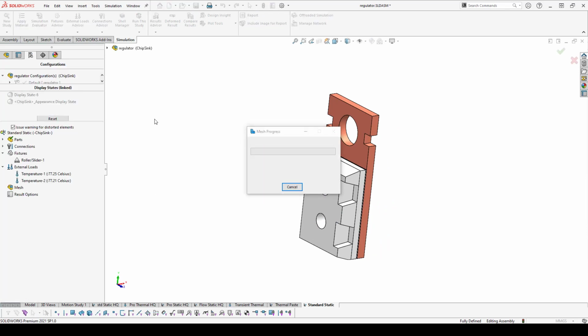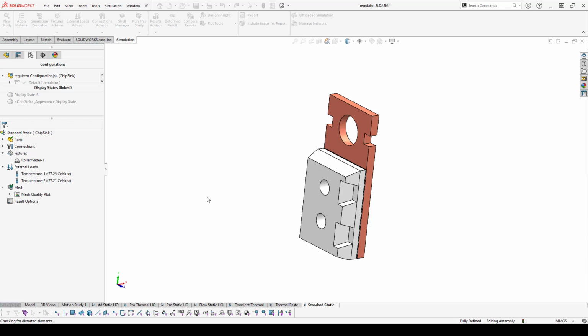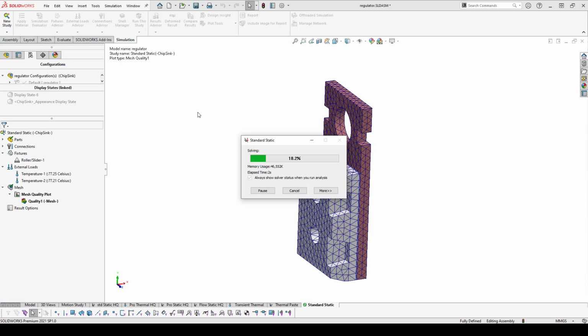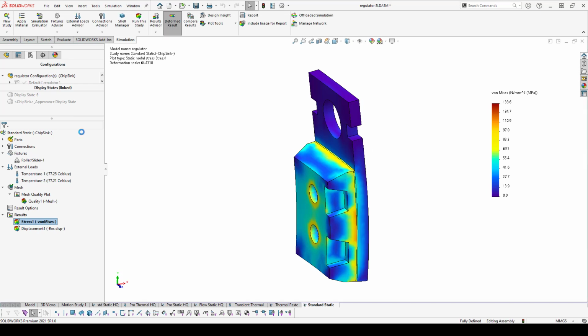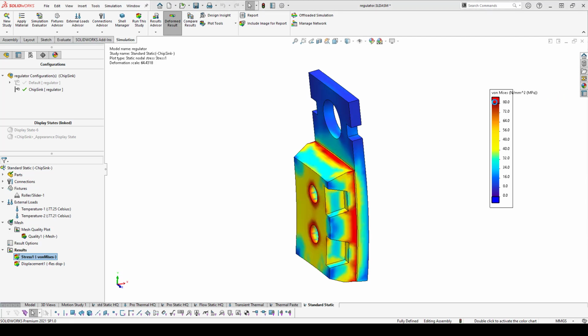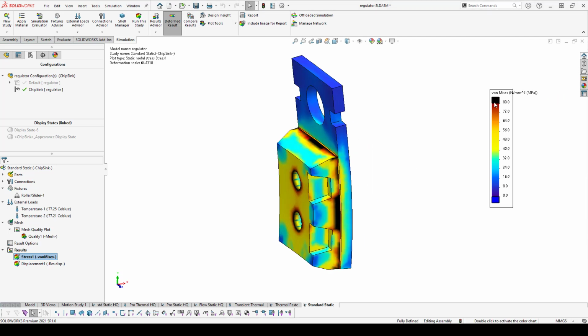Let's go ahead and mesh it and see what kind of thermal stresses we end up with in between those contact regions. The mesh I'm using today is going to be the blended curvature-based mesh, just using a default size for it. I'm not going to talk about mesh convergence and refining the mesh and all that. We're just going to basically look at average stresses so that we don't have to belabor some of those points for this short webinar here. And ultimately, I get some stresses, which I'll make a couple quick customizations to that I'll use for comparisons later on as well.